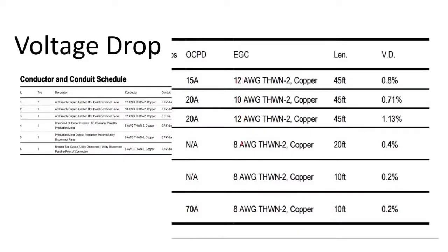You might be looking at this material list and saying, well, why don't we simplify it? And sometimes you can oversimplify, like using number 8 cable for every circuit just to only have number 8 cable. That could result in you spending too much money on your cable budget. But if there is just one oddball, saying, okay, well, there's 2 circuits of 12 and 1 circuit of 10, but look, this circuit of 12 actually has some voltage drop to it, and so let's make it a circuit of number 10 AWG instead, for voltage drop mitigation.